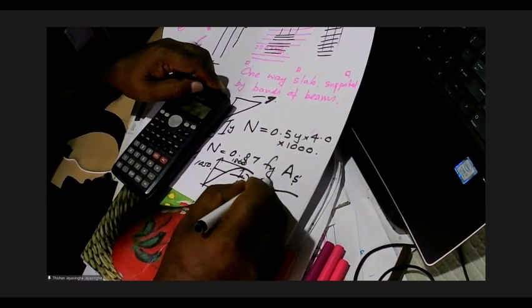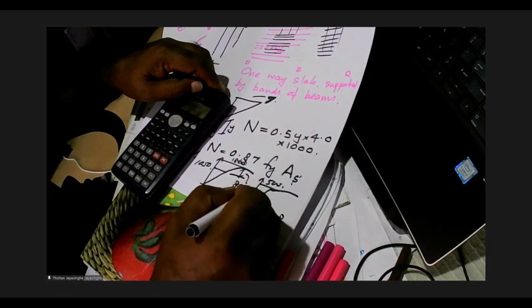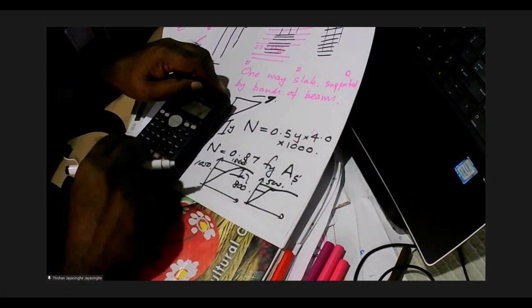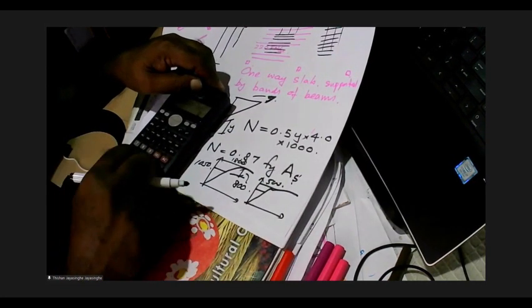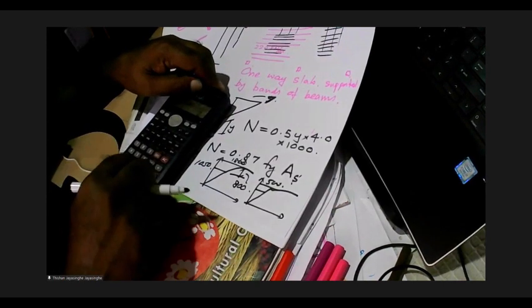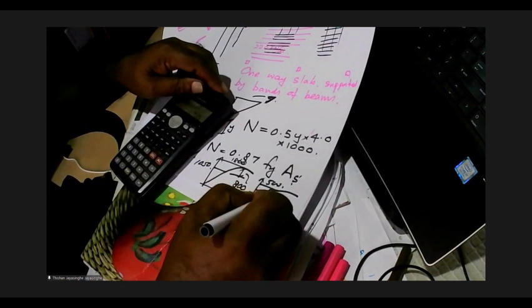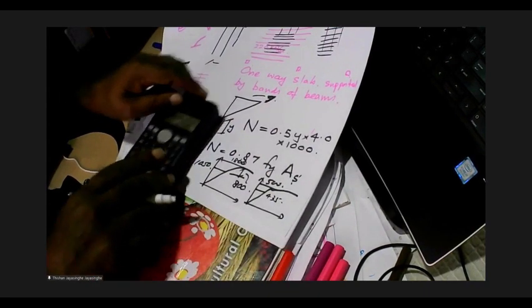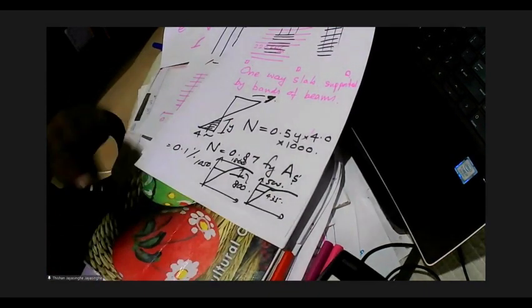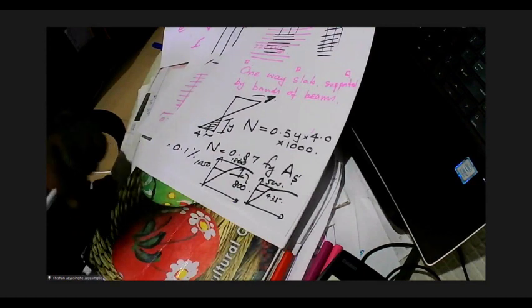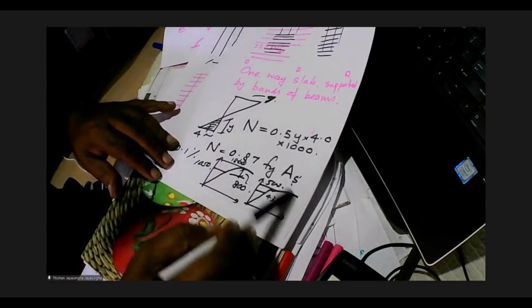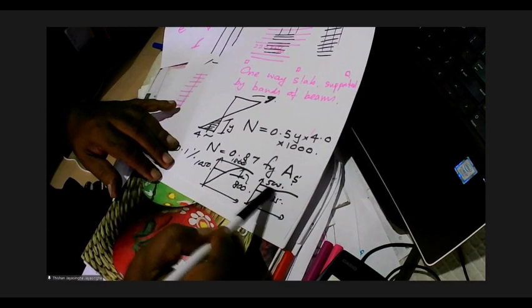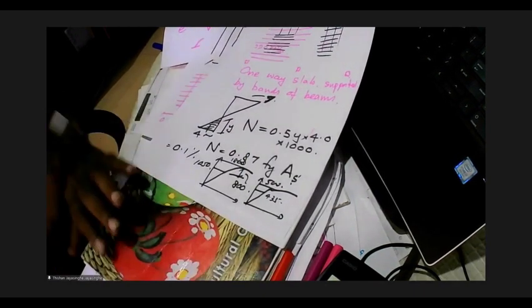Now what happens in reinforced concrete? We have 500 capacity. We go for 0.87. We had 434. Even under service conditions, we can go up to 434. So the behavior wise, here you have only a small margin, here you have a huge margin.